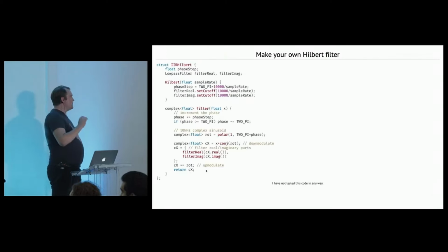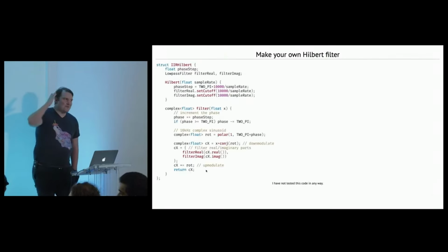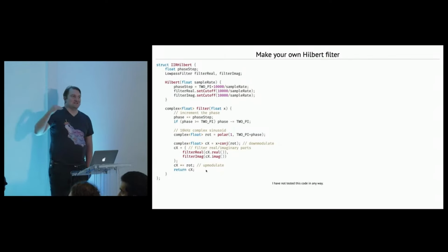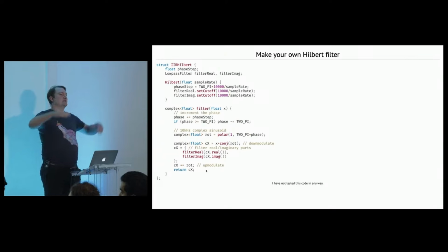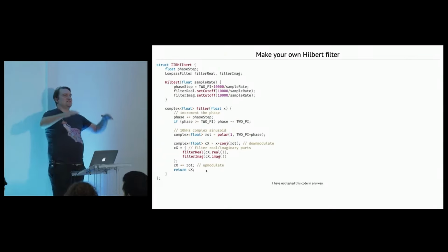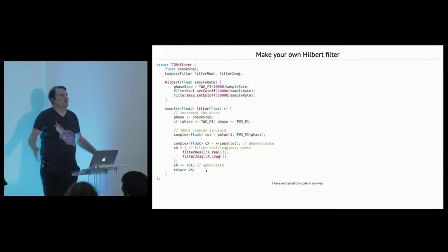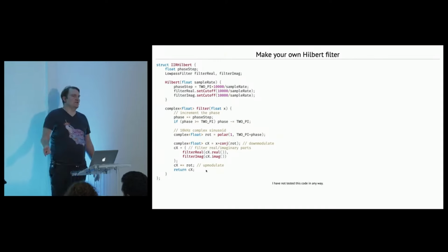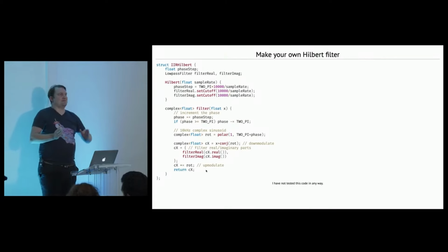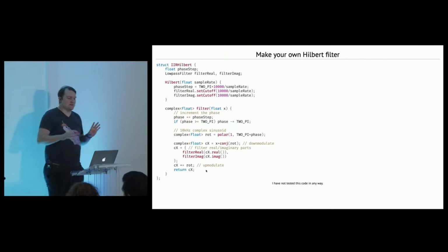So I will say, off the shelf, a biquad low pass is not going to cut it. The cutoff is nowhere near sharp enough. Because remember, typically the cutoff for a biquad low pass ends up at whatever it is, 10 kilohertz. So it doesn't matter if it's 100 hertz wide, or a kilohertz wide, in fact. Whatever that width is, it's going to be happening near 0. So generally, biquads are not going to cut it.